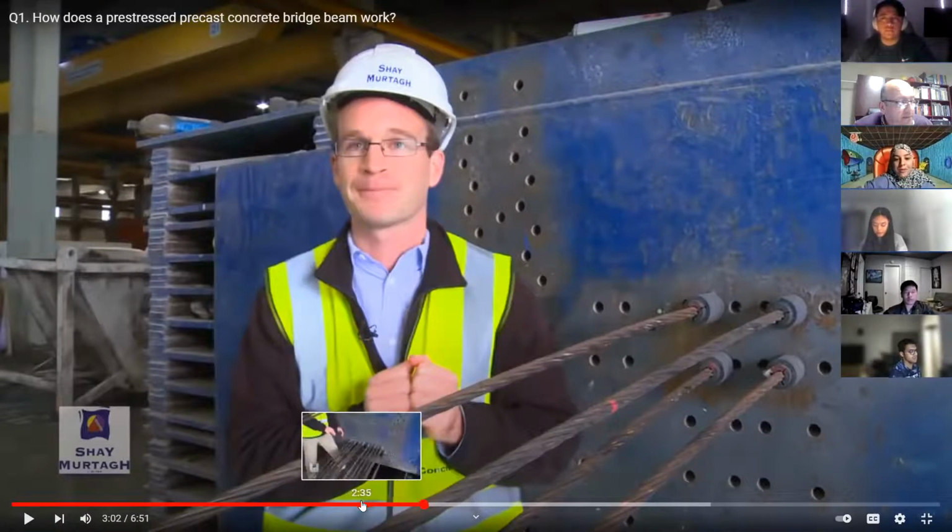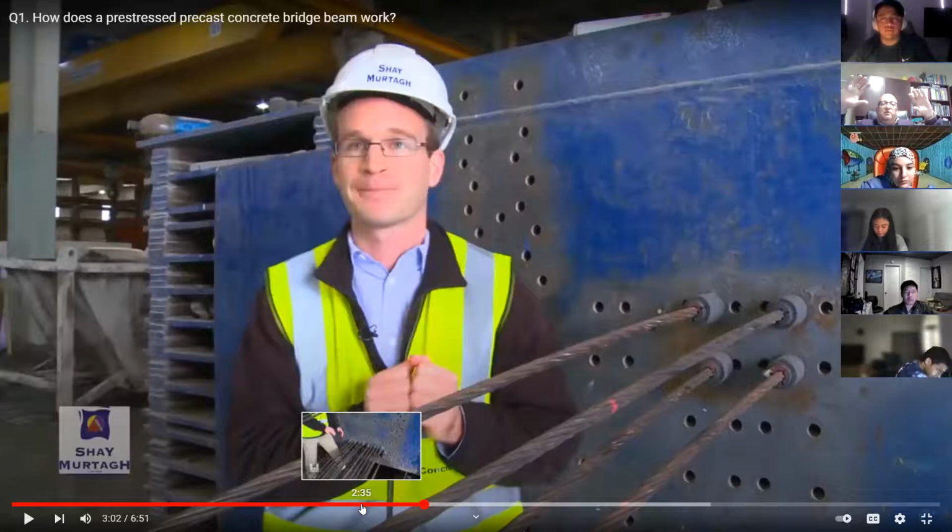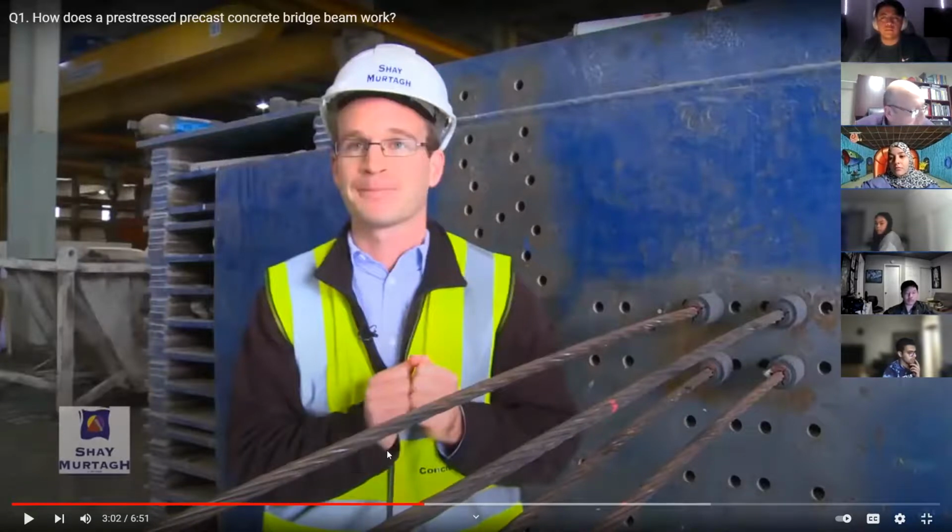Positive moment. Why? Because look at this frame that I stopped at. 2:35, 2 minutes and 35, right? What's going to happen there? You have more strains at the bottom. So when you apply the tension, it's going to be acting like this. It's going to be creating camber. It is pushing the beam up, so that when you put the service loads later on from the top, it's going to be taking it down. Negative moment. Yeah, so this here creates negative moment on the beam.